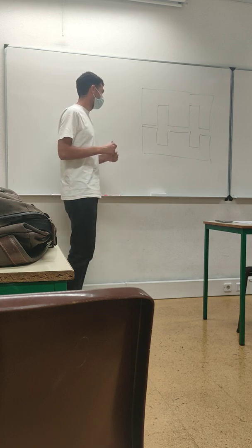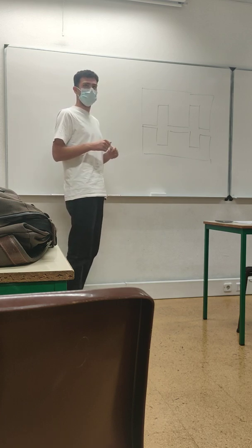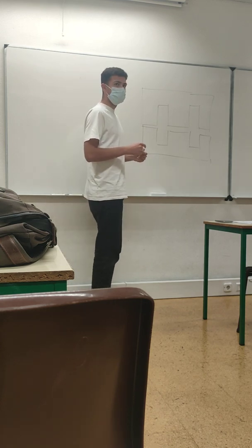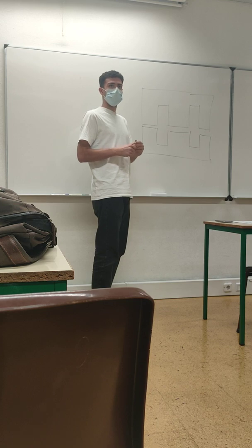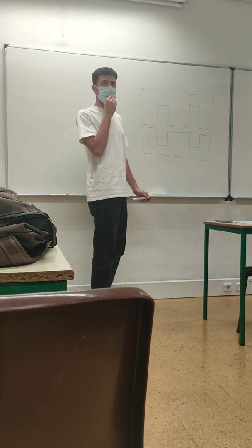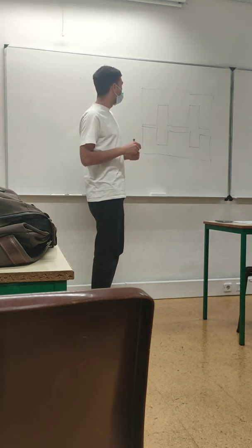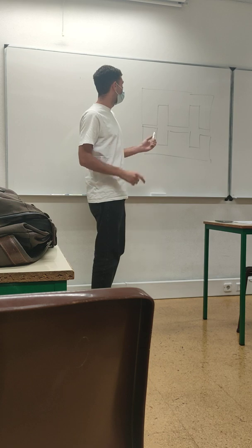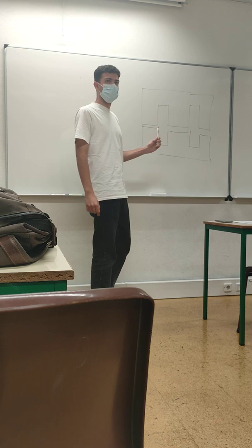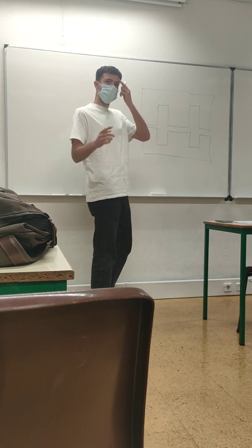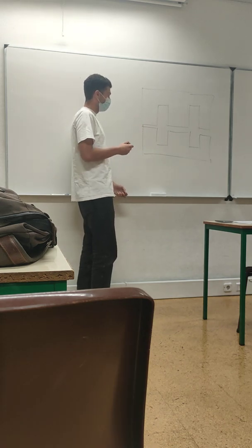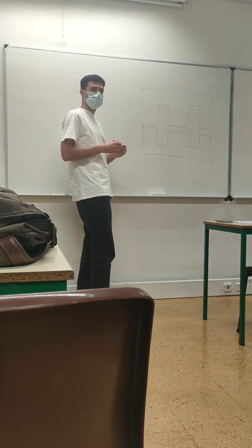My question is about calculating the B. Where? In the core. What means B? It's the density of the magnetic flux. And we have to calculate it for different voltages. The thing I want to know is if we have to calculate it using different permeabilities for the different areas of the BH curve, or if we can always use the same permeability, because what we want to know is the influence of the length of the air gap.